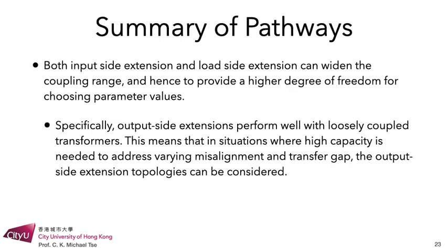And finally, for both the input side extension and low side extension, we are able to widen the coupling range and therefore provide a higher degree of freedom for choosing parameter values. In particular, the output side extensions will perform much better with loosely coupled transformers. This means that in situations where high capacity is needed to address varying misalignment and transfer gap, the output side extension topology will be very useful.